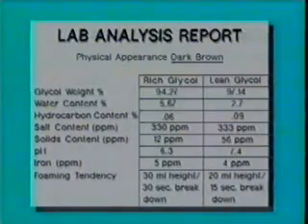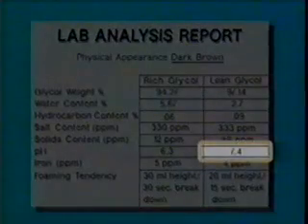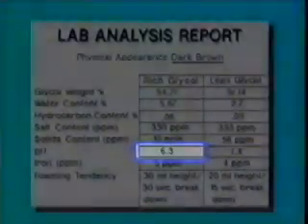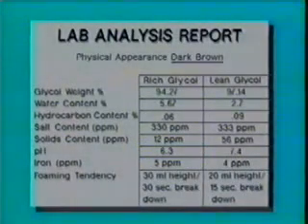In our sample, the pH of the lean glycol is acceptable at 7.4, but the pH of the rich glycol is too acidic. Check the pH of the glycol periodically and keep it on the alkaline side by neutralizing the acid compounds with alkaline chemicals.